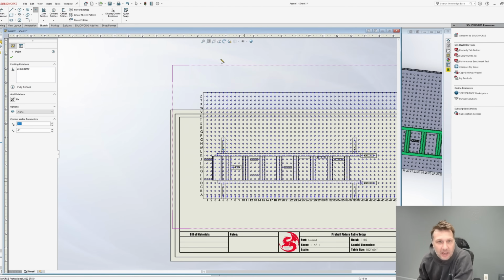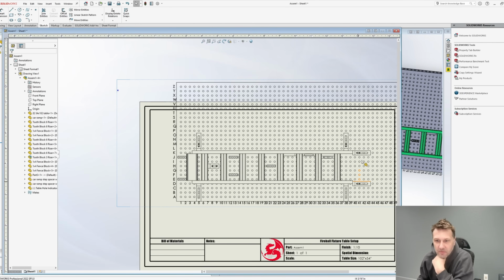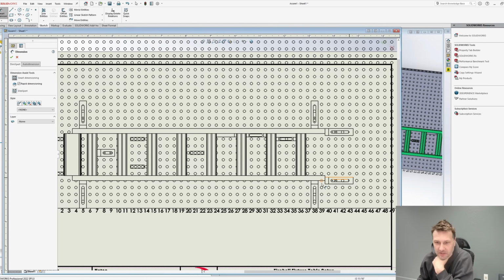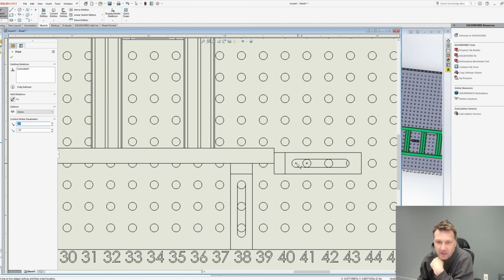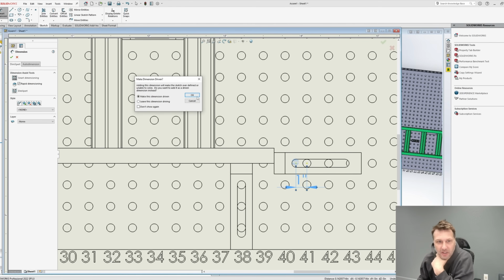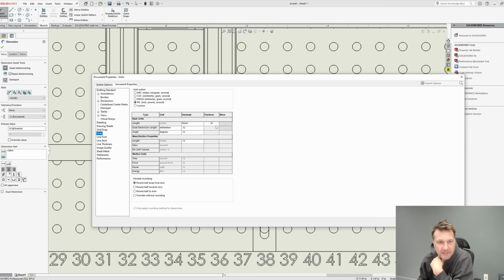And I know I'm giving you a lot of information here, but I'm trying to give you guys as many ideas as possible. So basically, we just need to map these out. And the way it works, like I said, this is a tooth block. It doesn't have any teeth in it for the model, but what I need to know is how far extended is it? And oh look, we're 1 inch. So I want to make sure that our map is in inches, and we're down to the 16th. So you can come over here and select this little icon down the bottom and go to 16ths, and we're going to round to the nearest fraction and hit OK.